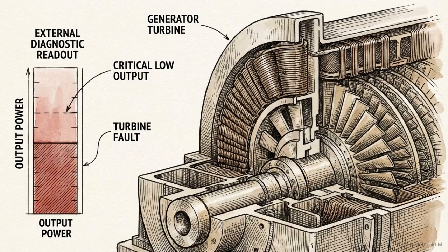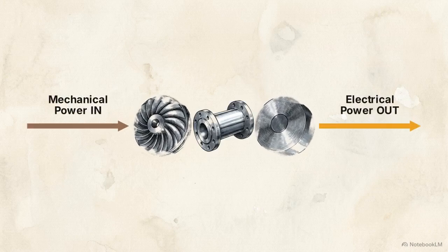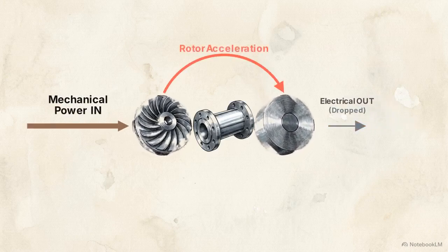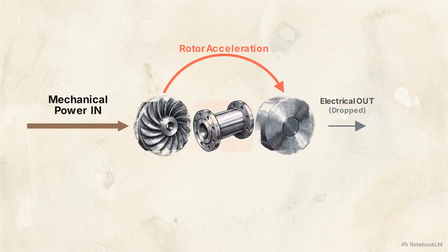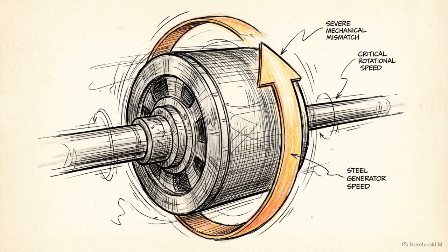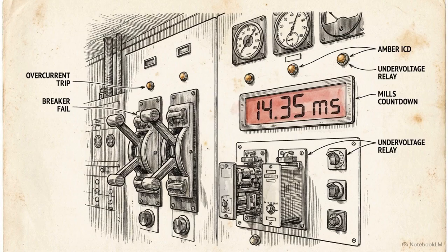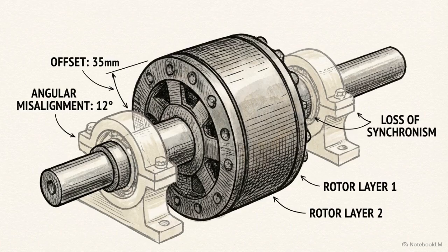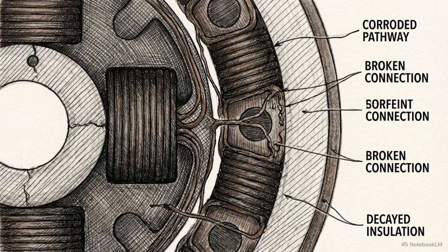While the physical forces decrease, the fault has now drastically reduced the generator's ability to output electrical power to the network. This creates a severe mechanical mismatch. The electrical power leaving the generator has plummeted, but the mechanical power driving the turbine remains completely unchanged. With more power coming in than going out, the massive generator rotor physically accelerates. Its rotor angle increases relative to the synchronous grid. The transient phase is a race against time. If the fault is not cleared before the rotor angle advances too far, the machine will suffer a total loss of synchronism.